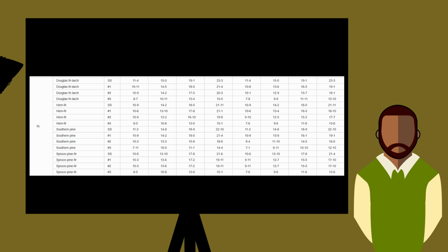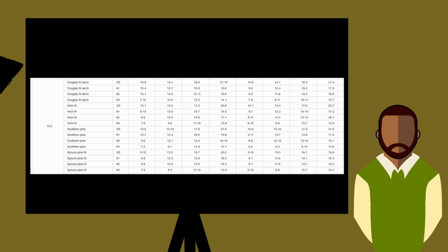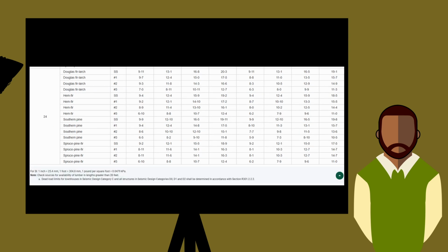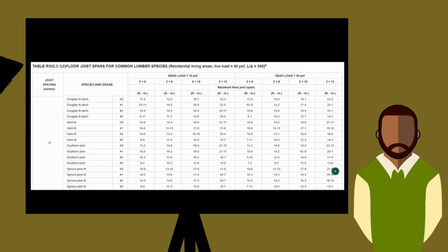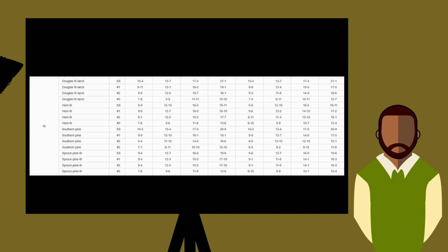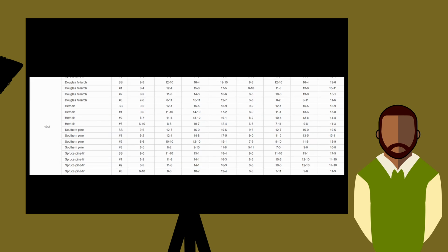Basically, this is 40 pounds per square foot or 30 pounds per square foot. Now, if you walk around in whatever space, 30 pounds per square foot is a 30-pound block that is 1 foot by 1 foot covering your entire floor space, right? 40 pounds per square foot is the 40-pound block.